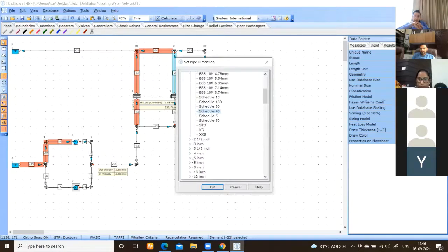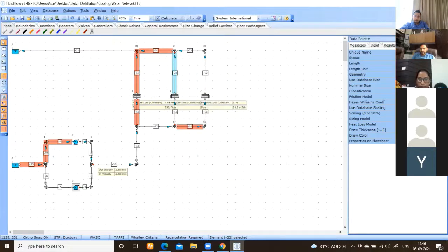The pump discharge is the first five pipe segments, those are 5 meters. Then other segments in the header are 50 meters. So in his file from pipe number 11, it is 50 meters. All right, we can run it now.